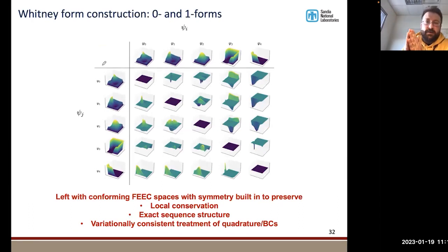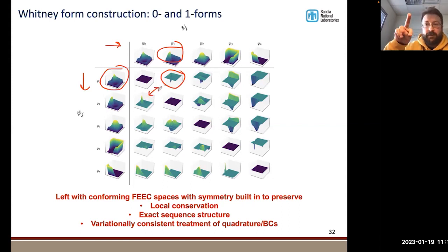Now these are the shape functions that correspond to the boundaries between those partitions of space. Along the top and along the side here, this is a set of POUs, and shown in the middle is the boundary that those two POUs share. For example, this is the boundary in between this partition and that partition. You can see that they're anti-symmetric. When you flip your perspective, boundary of I or boundary of J for face Fij, and the boundary of a partition with itself is equal to 0. So this is the construction.